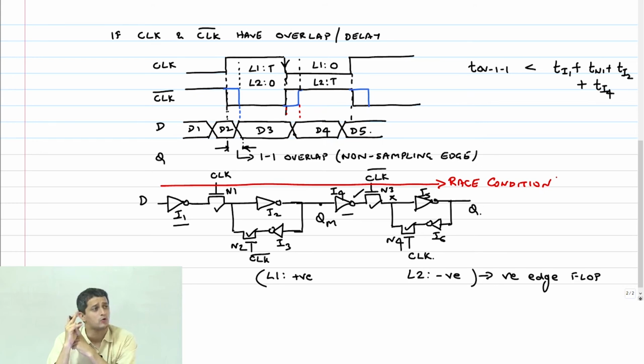No, what is T? N2 or N3? N3. So what happens? See, the thing is, there is a feedback inverter on the other side. Now, if this capacitor after N3 charges slightly above the trip point, then that feedback inverter is just going to hold that value forever. So to be careful, it is better to cut it off before.